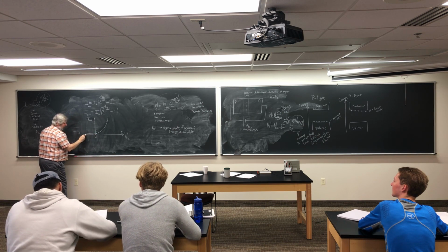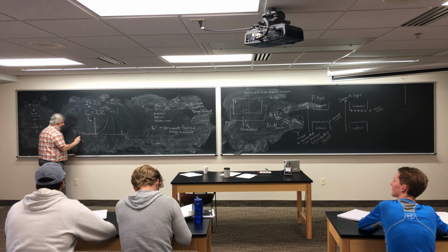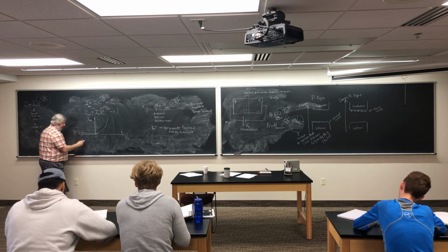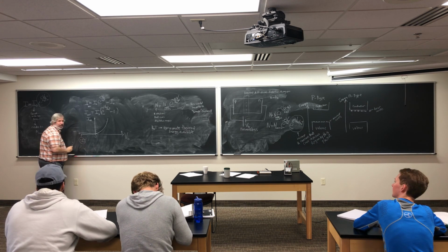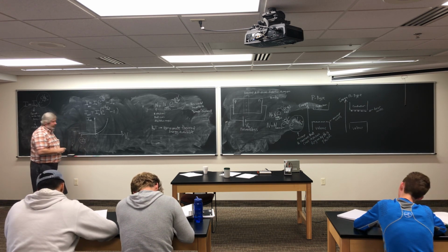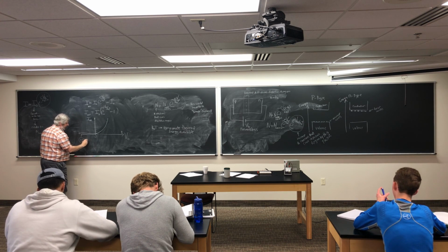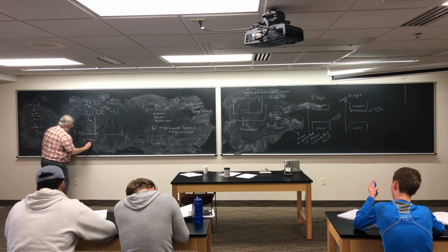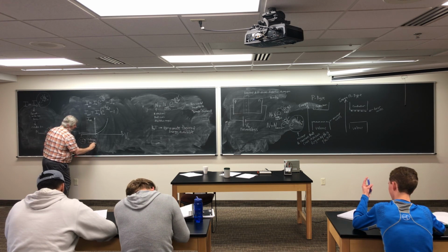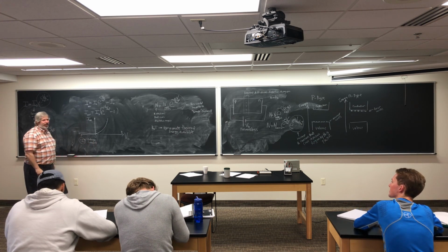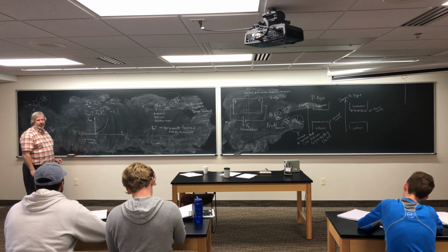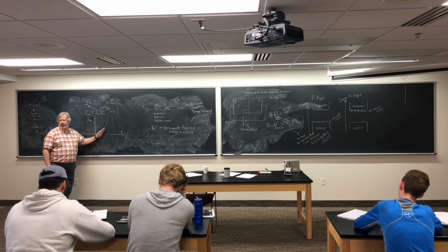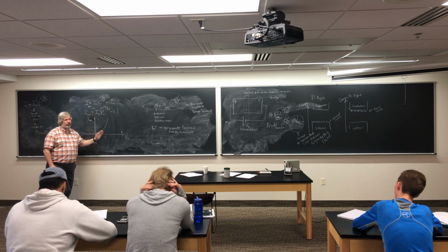And it's going to eventually saturate to this negative I naught down here. We call this the leakage current. So we call that I naught the leakage current. So when you reverse bias it here, you might get a little bit of current, but not much. But you get a big increase as you change the bias voltage if you forward bias it.